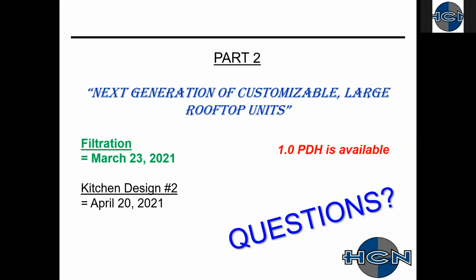With series reheat, you're limited to coming off the coil at about 74, 75 degrees. With parallel reheat, you can get up to about 99 degrees leaving air temperature off the hot gas reheat coil. I hope that helps explain a little bit, Pete, but we can dig into that and get you a more suitable answer.